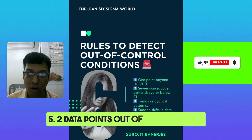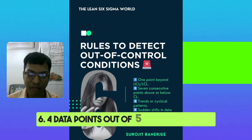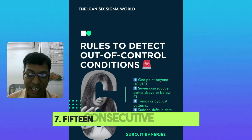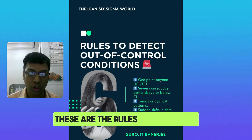2 data points out of 3 consecutive data points are on the same side of the average in the upward direction. 4 data points out of 5 consecutive data points are on the same side of the average in the downward direction. 15 consecutive data points are above or below the average. So these are the rules by which you can understand whether your process is out of control or not.